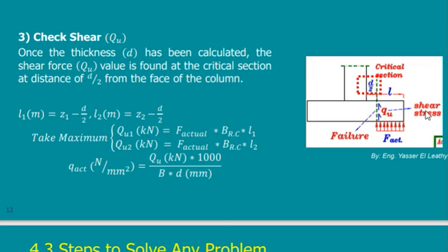But what is the difference? The difference will be in the cantilever from both sides. But if I take the difference between the length and breadth of the footing to be the same as the difference between the length and breadth of the column, then the cantilever from both sides will be the same. This is more economic. If you have a footing with the cantilever from all around with an equal distance, this is the optimum design for this case. Also it saves your time in design, because you don't have to design two directions, just one direction.